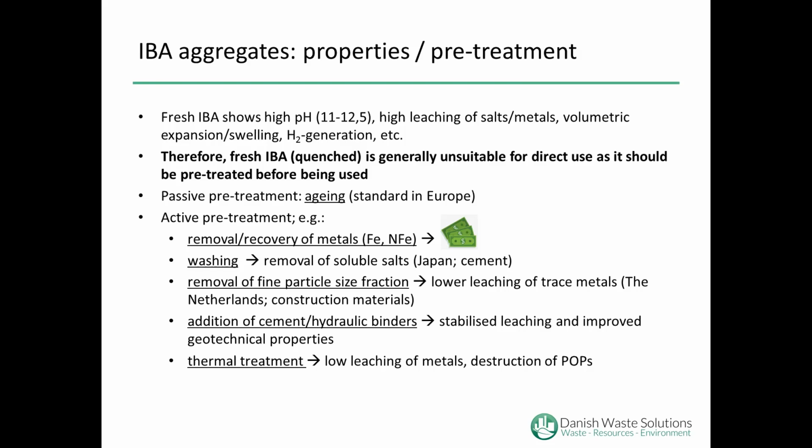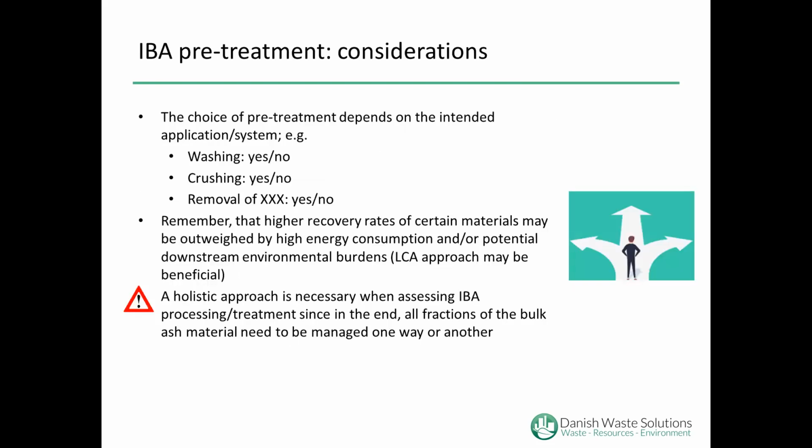The considerations regarding bottom ash pretreatment are that the choice of the pretreatment depends on the intended application, meaning I could have washing, I could have crushing, I could have removal of whatever, if it makes sense. And we should remember that always some high recovery rates of certain materials may be actually outweighed by high energy consumption and potential downstream environmental burdens.